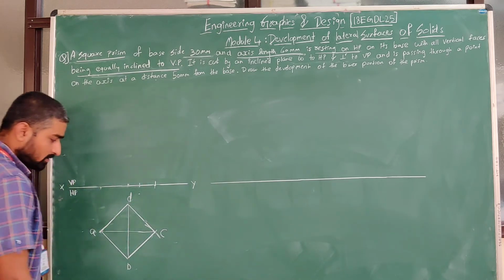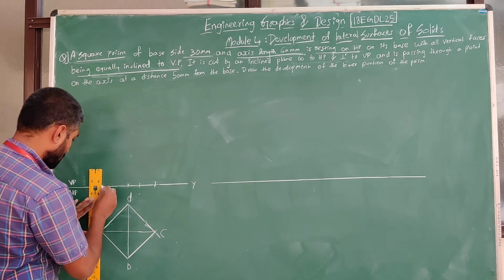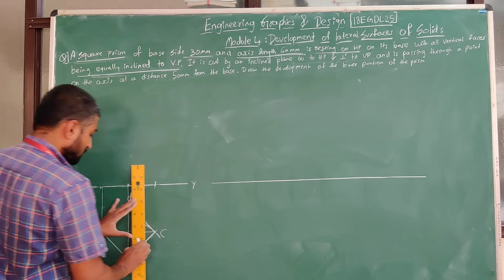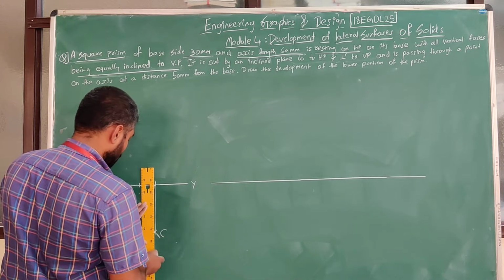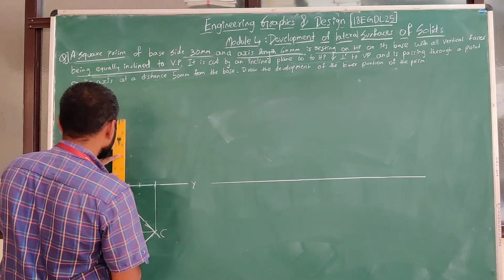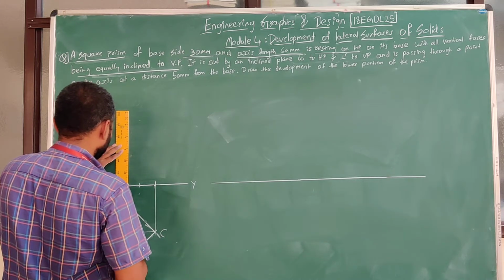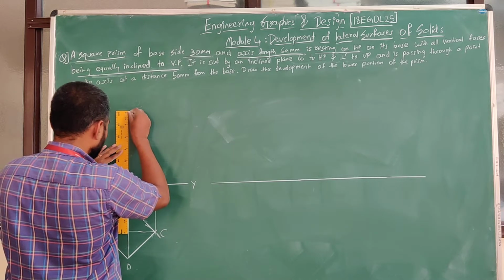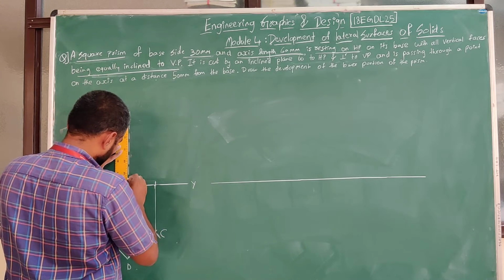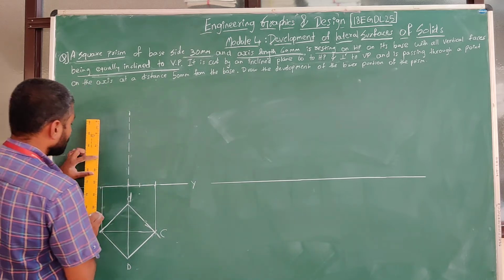Now, let us project this on the top side with very light lines. Please remember, the projection line should be very light. Then draw the axis height, that is, 60 mm, as given. I am going to draw the axis line initially as dotted. Once I get the 60 mm height, you close the prism.